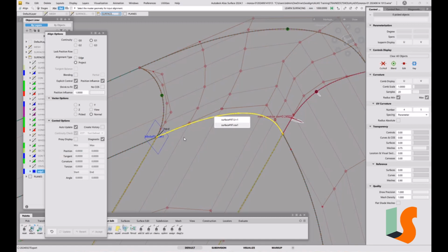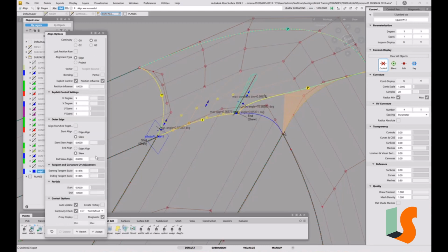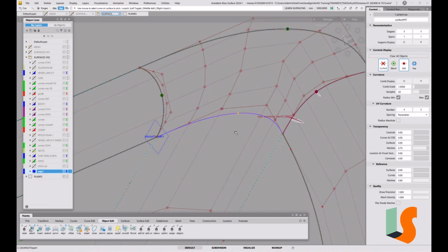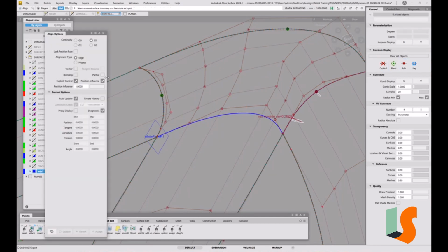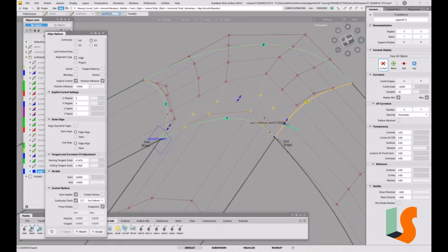That was a deliberate mistake. Can you see what the mistake is that I've done? I've got a curve on surface there, and it's because I had project on there by mistake. I should have had edge on. Let's revert that, so let's get rid of that curve on surface. That wasn't meant to be in there. So always, going from one surface to another like this, we always want edge on, not project. Otherwise we end up with that problem that I just created for myself.